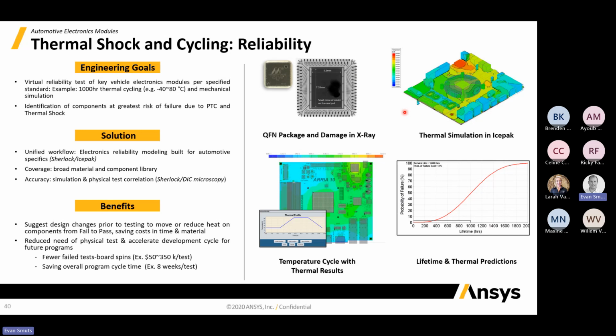So the idea is that there's a lot of tools there to help you deal with more common components, things like heat sinks and fans, so that there's only minimal input in terms of the simulation setup, things like your mesh settings and solver settings. A lot of that is taken care of in the background, so that we can focus on just the performance of the electronics instead of all those other settings.